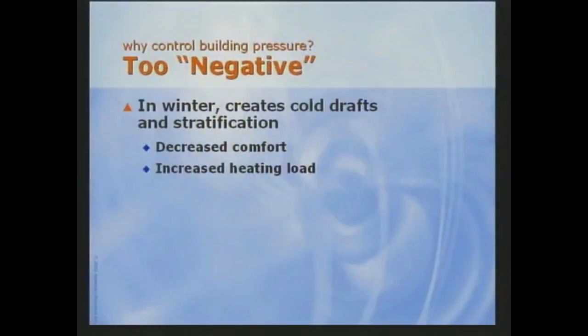Poor ventilation can result. A little infiltration may actually be helpful in the winter when outdoor air is dry. It can help keep the building envelope dry. But excessive winter infiltration means cold drafts, cold feet, and general discomfort due to poor temperature control. It can also mean cold spots in the space and the ceiling plenum where moisture can condense and mold can grow. Winter infiltration also increases the heating load.